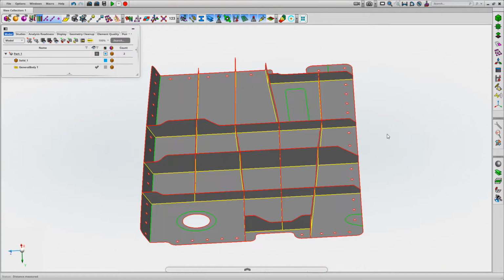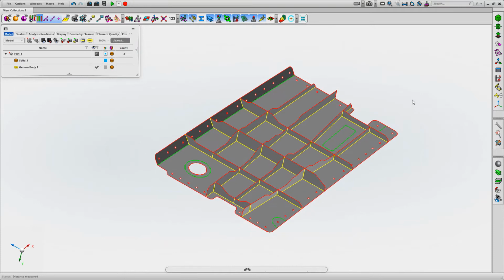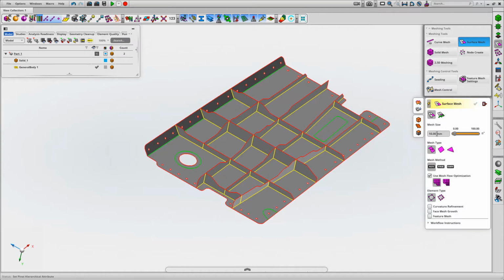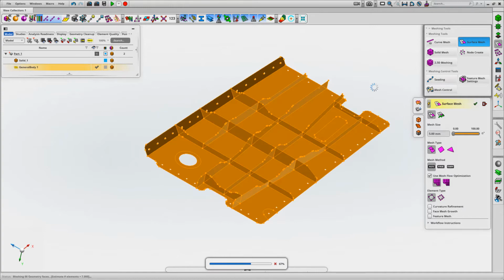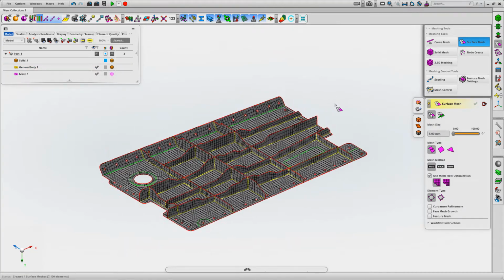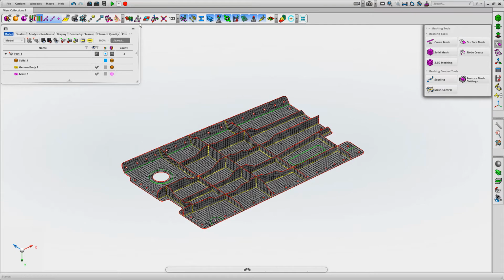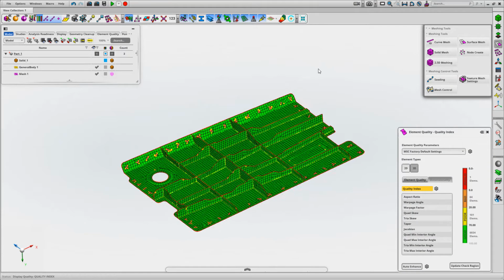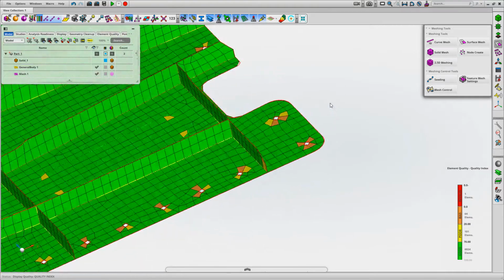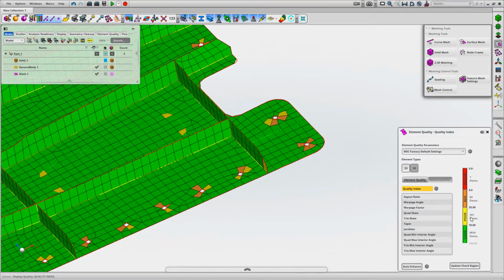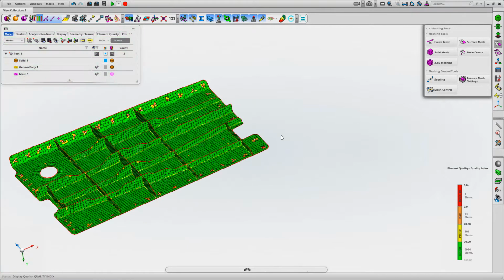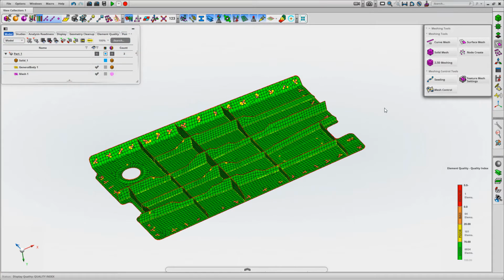Okay. So a couple of things with meshing. Obviously, we want to use it for defining the underlying FEA model, but it can be useful to show any problems with the underlying geometry. All right. So if I set the mesh size to 5 mil and then a mixed auto algorithm, it develops the mesh very quickly, and then I'm going to now check the element quality. Okay. So you can see here, green elements are good, poor elements in yellow, bad in orange, and then we've got one invalid element. Okay, so one element in that model is problematic.